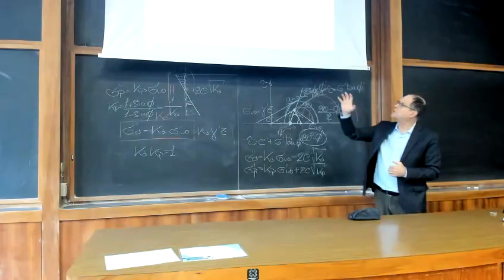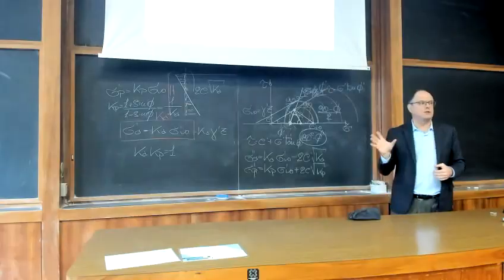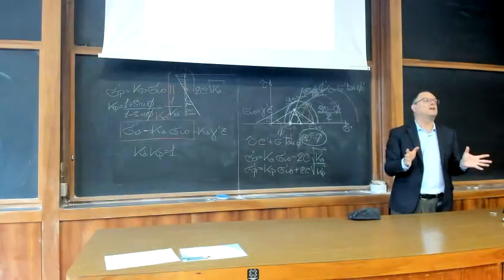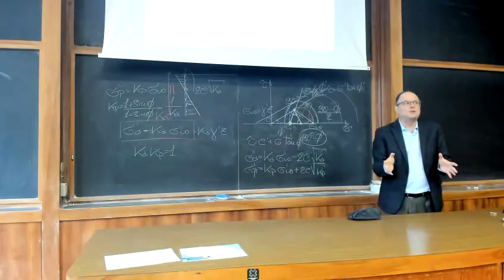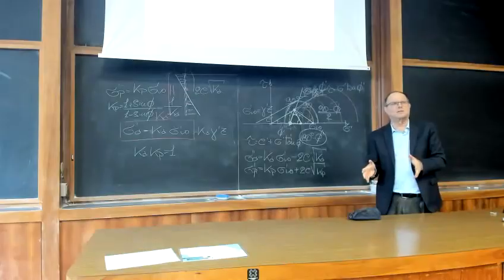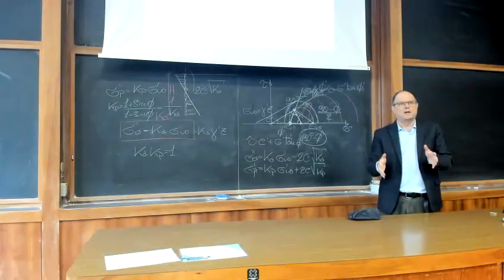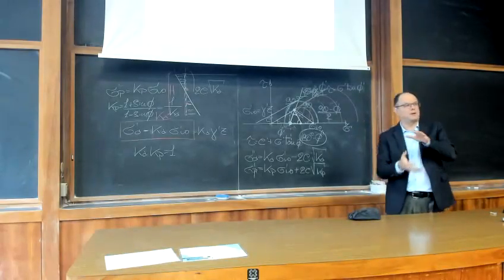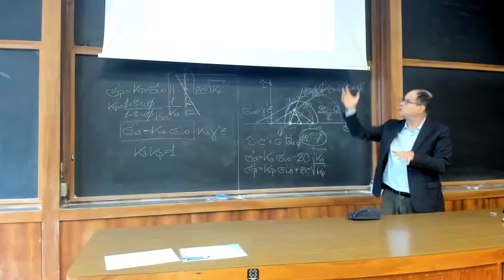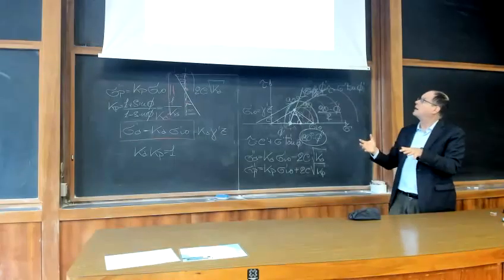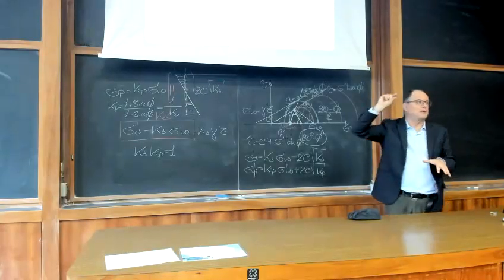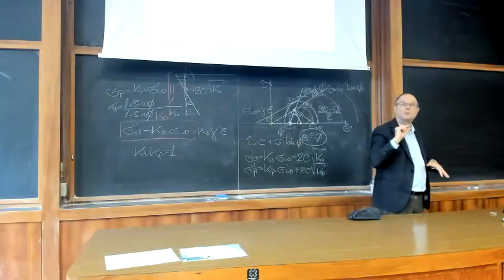And this is something which has to be considered very carefully, because most of the problems that you can find are not related to a matter of bearing capacity or excessive working loads. You have cracks on your building because the foundation is moving, because the soil is moving itself, just because you have selected a DF, a foundation depth, which is too small.